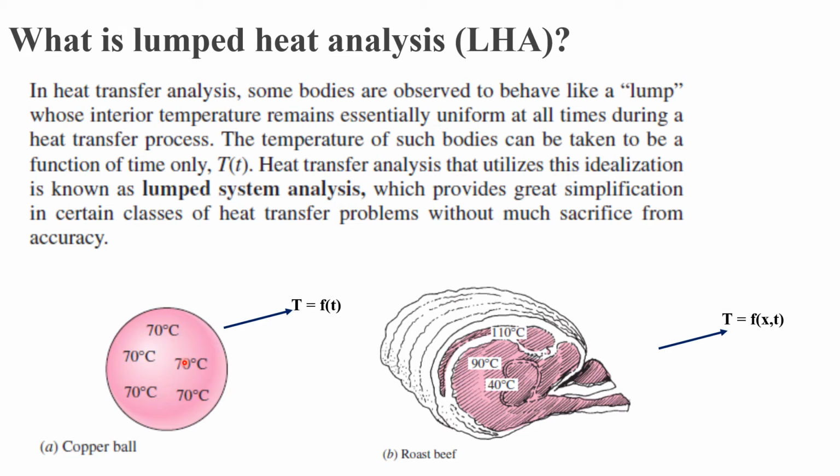So many transient heat conduction problems can be simplified to lumped system analysis. Here temperature is a variable of only time, which can be easily solved. That is the concept of lumped heat analysis. It is also called LHA many times. Please remember that.